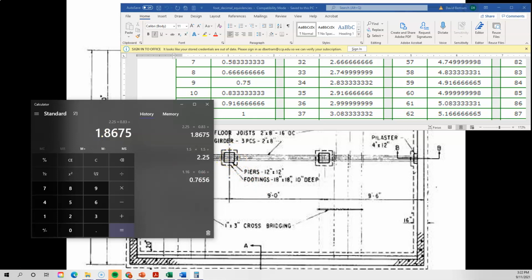And then if we want to translate that into cubic yards, like this number is plenty small as it is, but ultimately everything becomes cubic yards. That's how we order the concrete from the concrete plant. So we would divide, well, let's say there are 2 of them. So let's multiply this by 2 actually at this point. That's what we would do. The quantity would go in. Times 2 is 3.73.